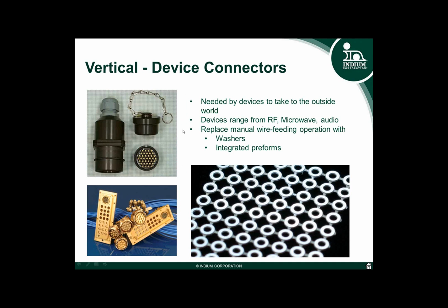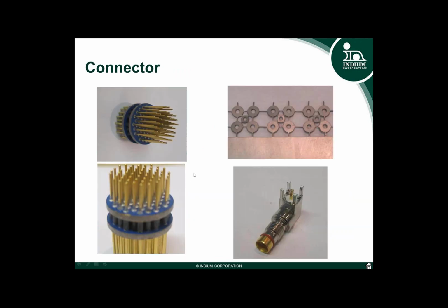We see these being used in many verticals at the moment, but we see them used in military avionics where these multiple array connectors are used. Again, looking back to Bob's past for solder feed-throughs, you can see this connector here has got a multitude, and also there's a ferrite bead standing up in this grouping assembly here as a filter on this connector type as well.